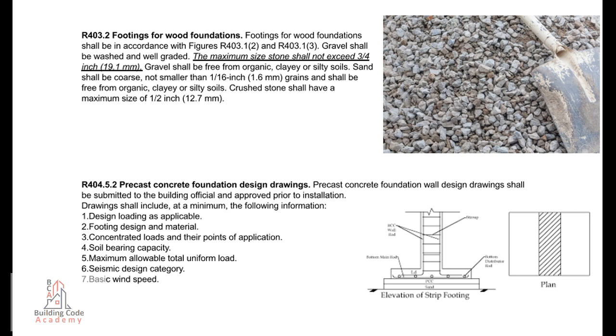Gravel shall be free from organic, clayey, or silty soils. Sand shall be coarse, not smaller than 1/16 inch, 1.6 millimeter, grains, and shall be free from organic, clayey, or silty soils. Crushed stone shall have a maximum size of 1/2 inch, 12.7 millimeters.